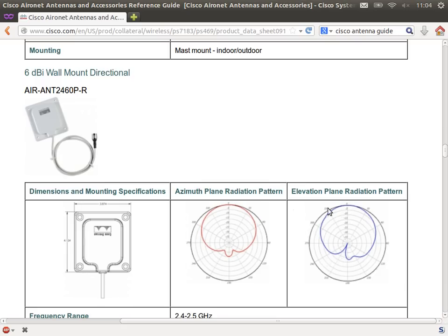Slightly different patterns. So depending on what area you want to cover, you choose the antenna which will give the signal strongest in that area. If you want a wireless access point to cover just this straight down here but not in the corners, so if you use your laptop in this area you can access, but here the signal is very weak, then you'd buy an antenna and mount it here, and you'd choose one which has a pattern such that the signal goes strongest in these areas and it's weak in these areas. So depending on what coverage you want, choose the antenna pattern.